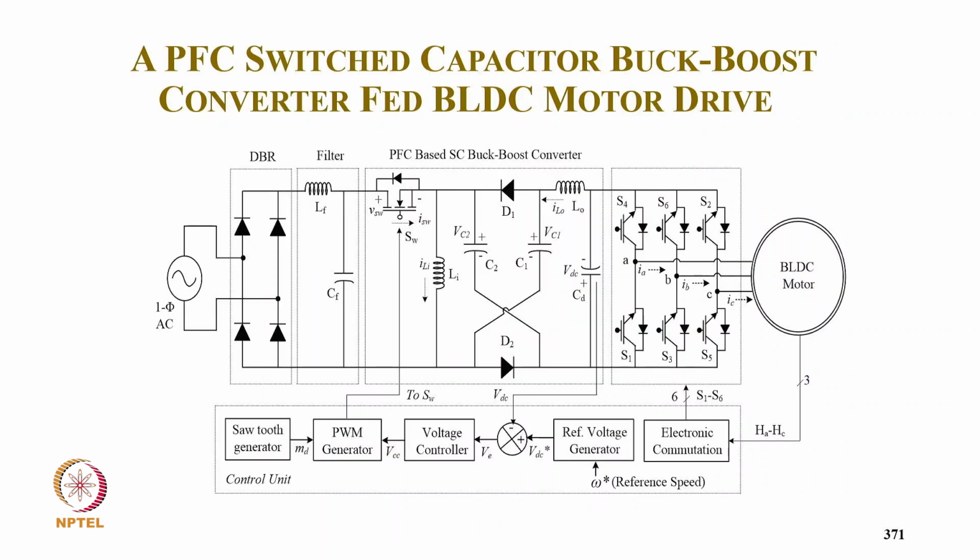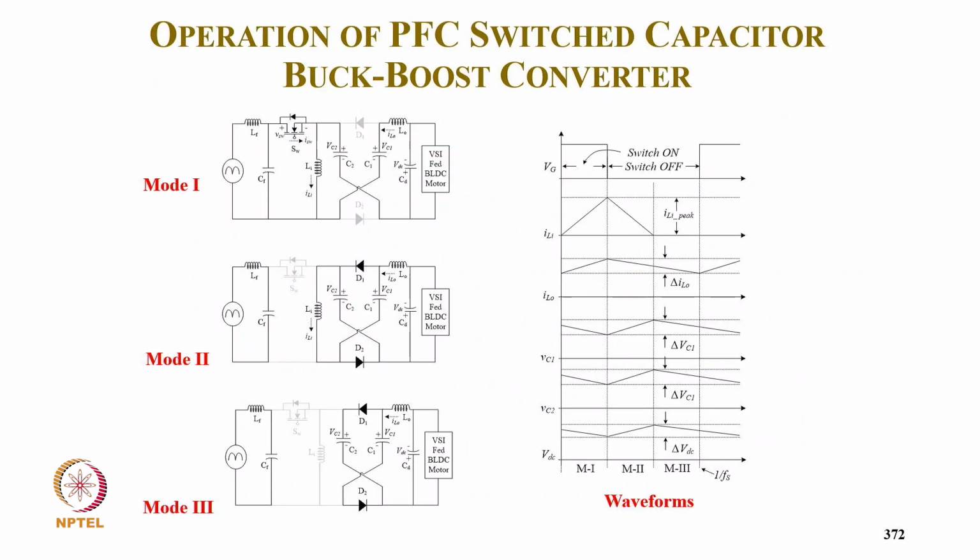So this is another converter, switch capacitor buck boost converter. I mean, typically control is similar. We design again in DCM mode, and in the control we don't sense input voltage, input current. We sense only DC voltage and the position for electronic computation, and winding current of the motor is also not sensed.